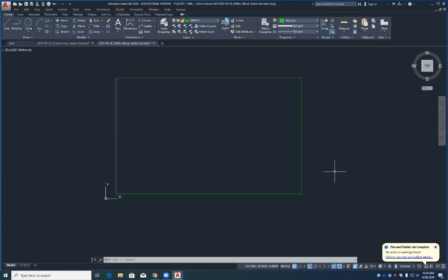Okay. So now we're going to go ahead and draw this as this drawing calls for right here. You've got to be careful. We've got to follow these instructions explicitly. So first of all, let me ask you a question. This hole right here in the top view, where is the hole located up and down this way? 1.38. Up and down. It's 1.38, yes, over this way, but up and down, where is that hole located? 1.315.